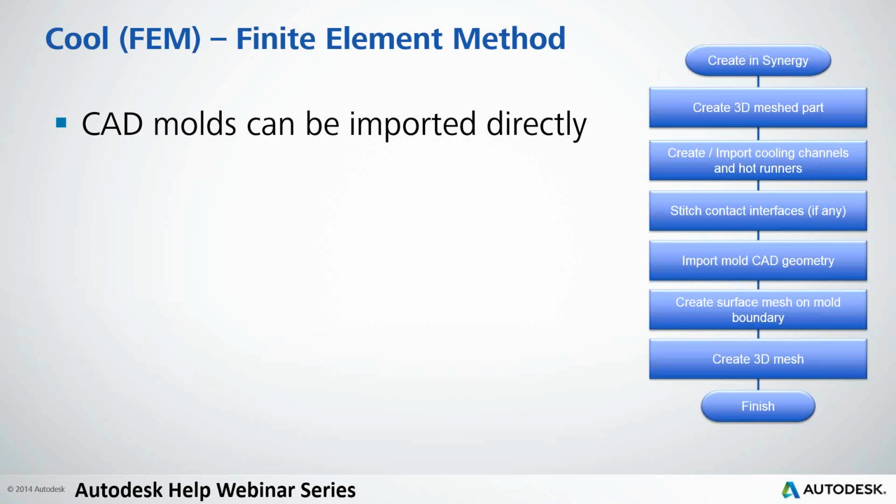If we are defining some mold inserts, we will need to define or stick the contact interfaces, and then we could import the mold geometry. First, we create a surface mesh of the mold itself, and in a second step, we create the tetras inside of the tool, and then we could start the simulation.